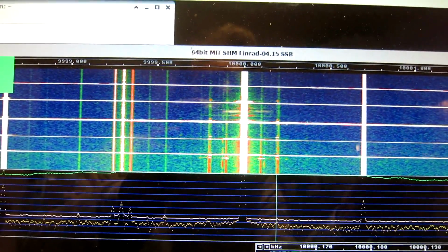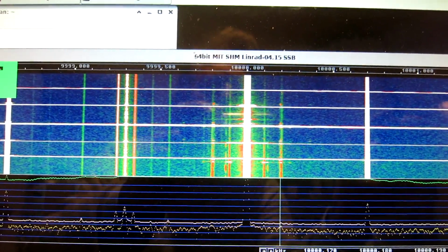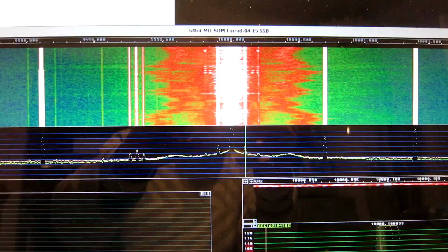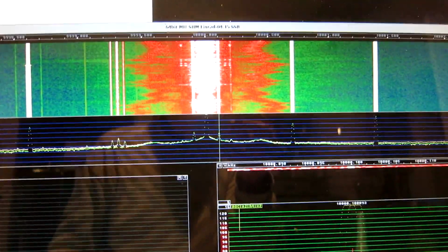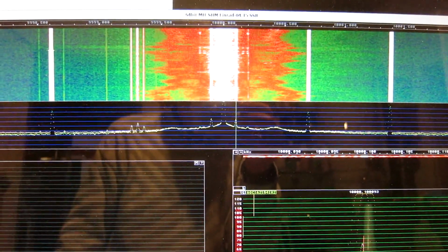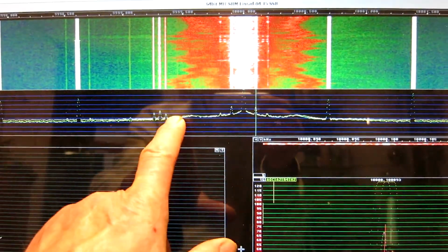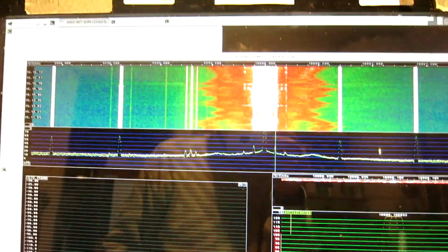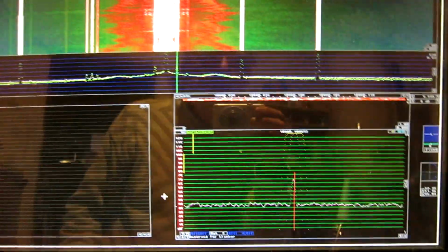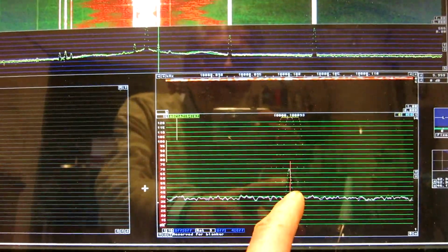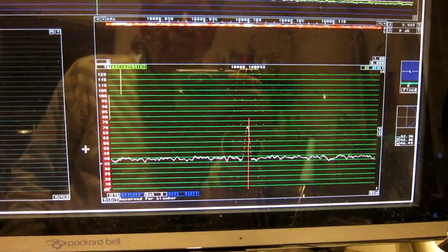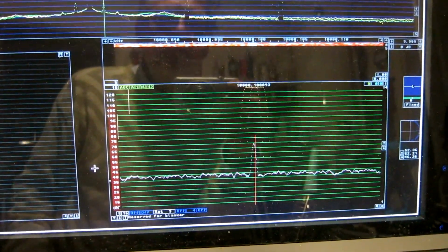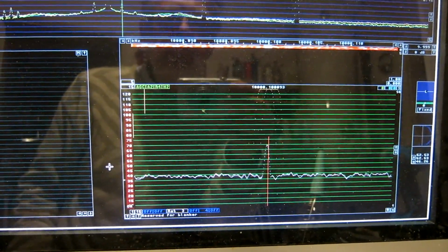So I will look at a couple of other crystals before deciding how to proceed. Here is another crystal, my number 161. It is more noisy and it has these ugly sidebands that travel up and down, as you can see. There is also, at an offset of 100 Hertz, a very narrow spur. This is because of my local magnetic fields. It's the overtone of 50 Hertz.